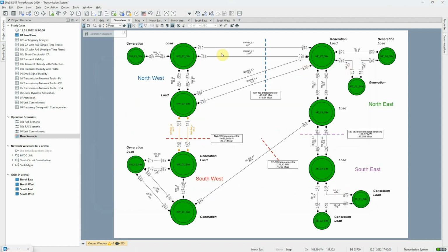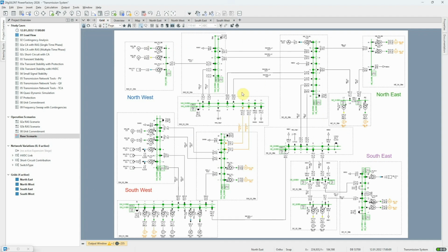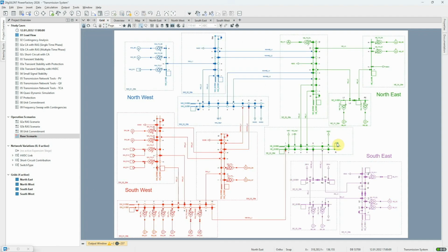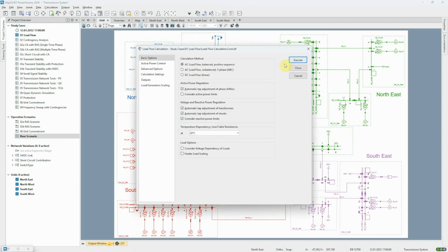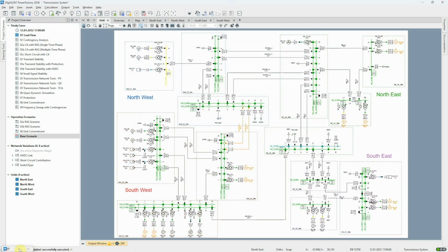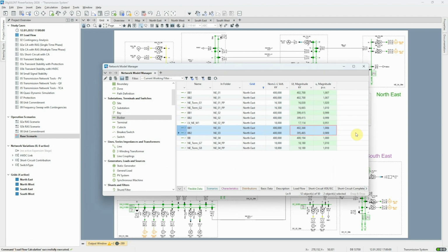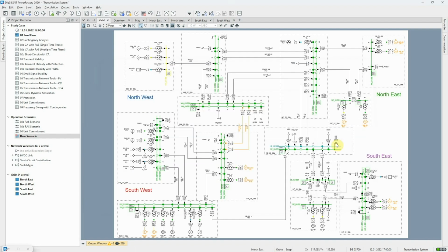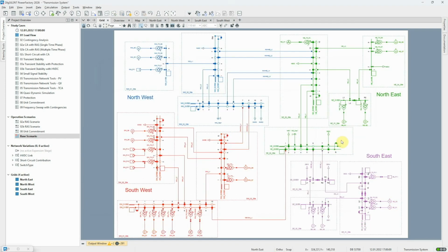We can split the substation from the grid graphic by double-clicking on the bus coupler to open it. We rerun the load flow. And we can see how the voltages are now quite different on the 2 sides of the split. The breaker is closed again.